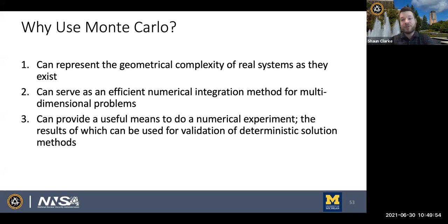So complex geometries do take more time in Monte Carlo, and there's really not a way to mitigate that other than not using more cells than you need to. So be judicious in the geometry that you're setting up, and make sure you're modeling only the portions of geometry that really contribute most to the tallies and quantities that you're interested in.